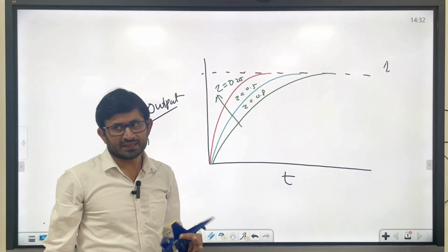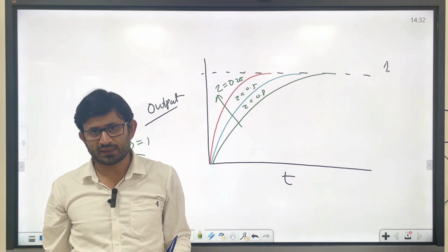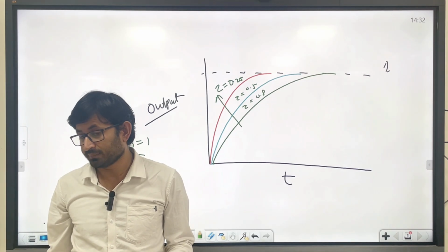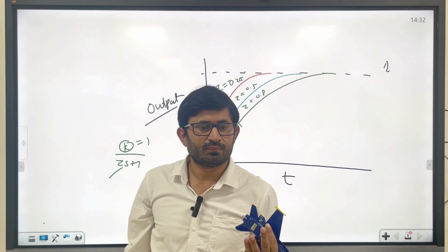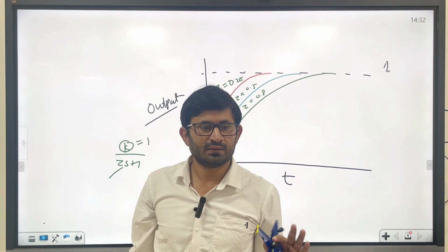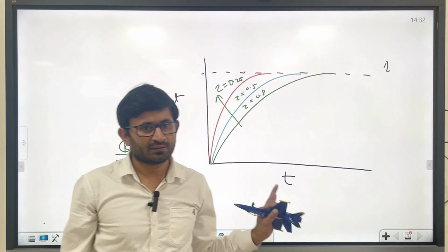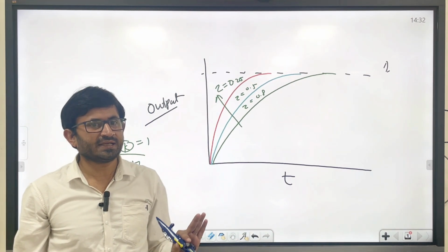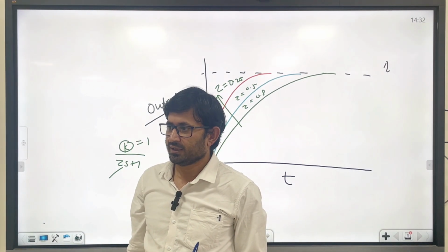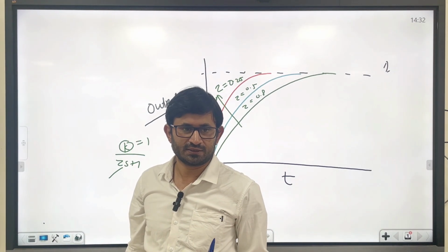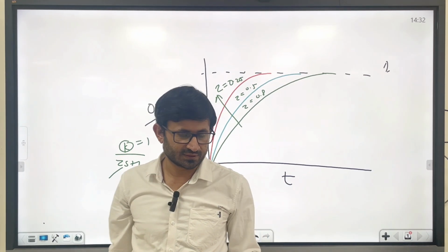Now this is all about the actuator dynamics, but the second thing, which is a very important part, is delay. Delay is more important than the other part. Right? For example, delay decides how robust your controller is. Delay directly affects the gain margin and phase margin.